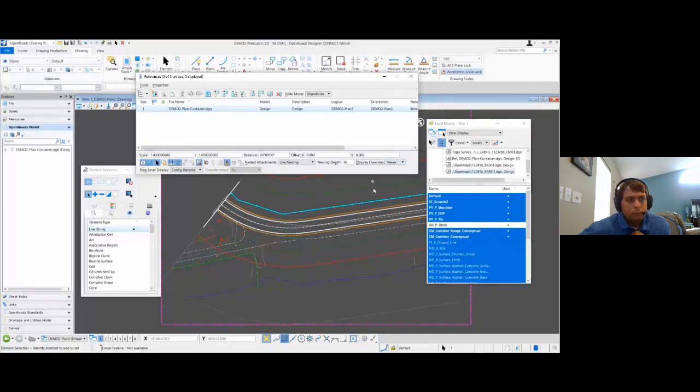So now, let's bring in the do not override variable, right? The key to remember is that it's controlled globally, but it also includes the direct reference. So if I go to my design model and I turn things off globally, when I come into here, my drawing models, all of them will be off globally as well.